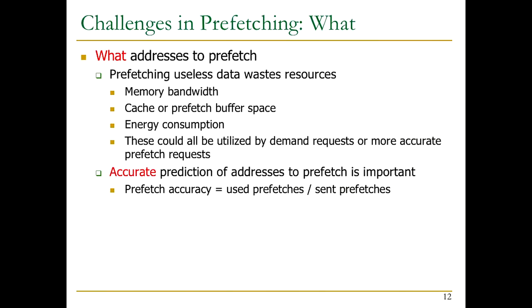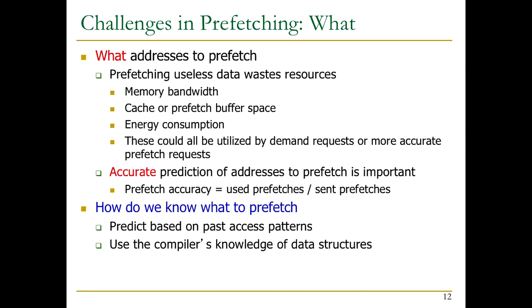And prefetch accuracy is the one fundamental metric, which is very simply, how many prefetches did you use out of the ones you've sent, divided by how many prefetches did you send? Simple, right? It's not the only metric.